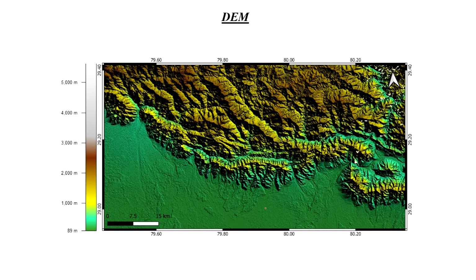Although this is a SRTM DEM, here you can see over this area these are all the elevations which are coming due to the vegetation. So this is a kind of DSM, but when you remove this error, the elevation coming from this vegetation, that will be your DTM, digital terrain model.